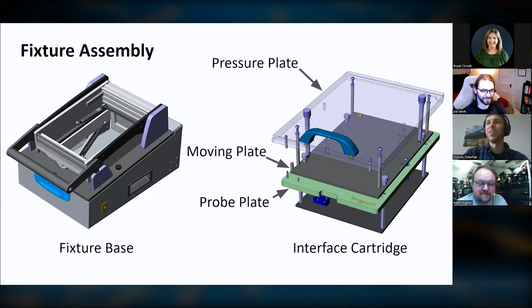Yeah, that's very true. One of the things with manufacturing files that we've seen from Altium and Mentor Graphics is ODB++ and then IPC-2581. They're both manufacturing file formats, and they both contain a lot more information about how to test and manufacture a circuit board.